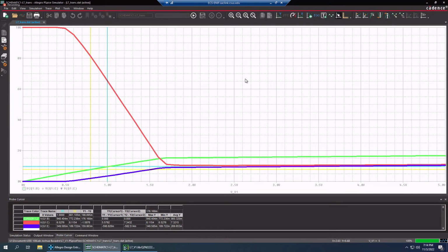So if I take the ratio of that, I have negative 1.59 volts divided by 0.182, which gives me 8.7. So it says my gain is minus 8.7. So that's close to the 9 that we saw when we did the transient. But that basically shows you the gain.